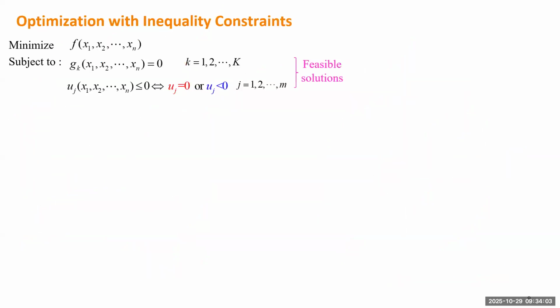All right, so next step, we'll add a new type of constraint, inequality constraints. Inequality constraints could be like a generator, which has to operate within its operation limit, like a generator with a capacity of 200 megawatts, and its power has to be lower than or equal to the 200 megawatt limit. So then we can use inequality constraints to model such a condition requirement.